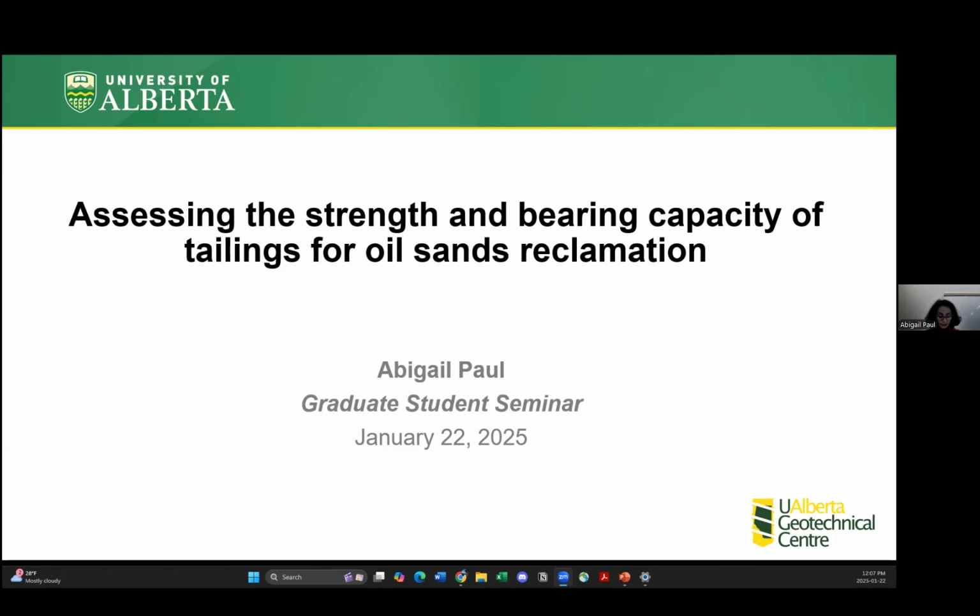A laboratory testing program and a review of existing published data was undertaken to investigate key properties of oil sands tailing for capping with a focus on the use of indexes to predict geotechnical properties. The results of this research program support the idea that index properties such as Atterberg limit can provide a cost-effective method for long-term monitoring and a preliminary design of cap deposits.